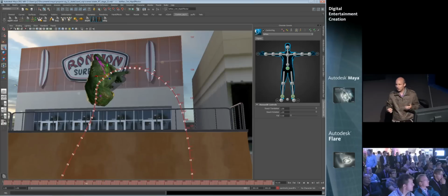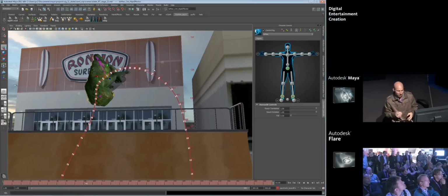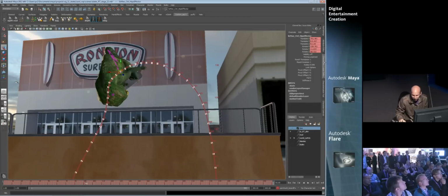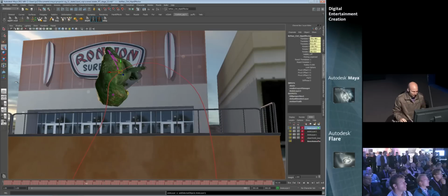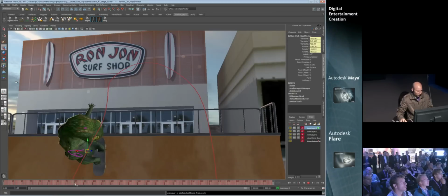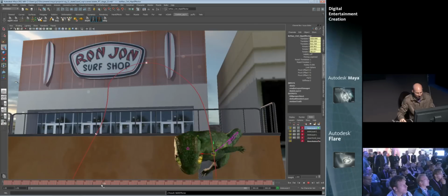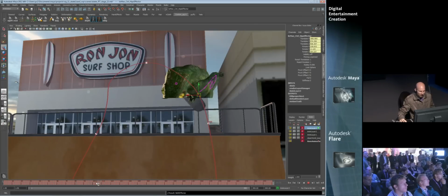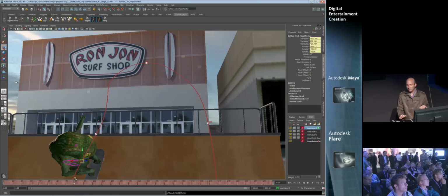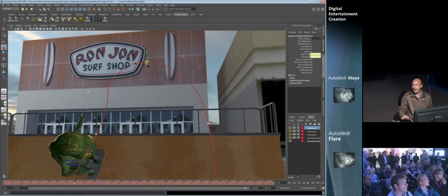So what we're going to do is make a new animation layer, and introduce that modification or tweak on a separate layer. There are two advantages of doing this. Number one, it gives me a very high-level control. I'm just setting a keyframe there, a keyframe there, and a keyframe there. So now I have a very high level of control over dense data. I've got 3 keyframes, and it's an editable motion trail.